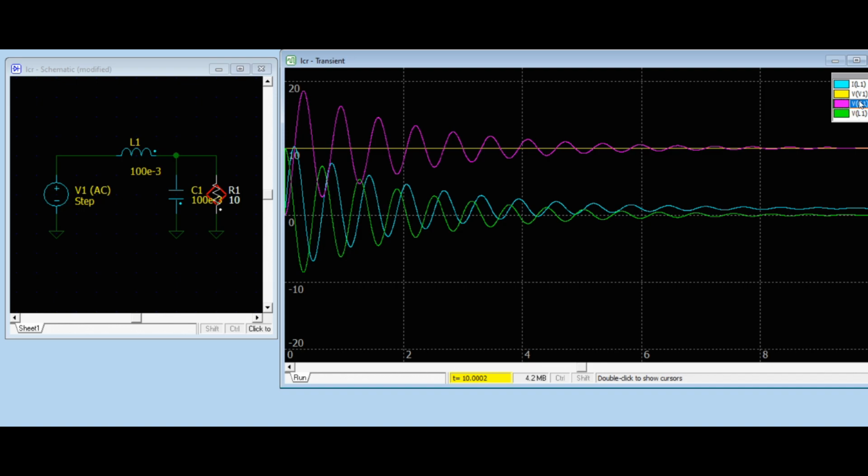Circuit behavior. Capacitor voltage reaches source voltage. As the capacitor charges, there comes a point where its voltage equals the voltage of the step source, 10 V. At this moment, the capacitor is fully charged. Current flow stops. When the capacitor voltage matches the source voltage, the potential difference across the circuit elements decreases, causing the current flow to stop.